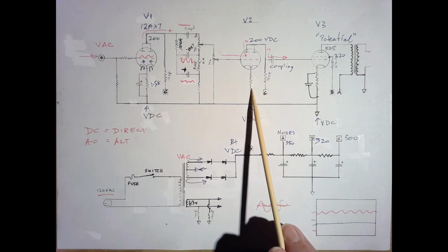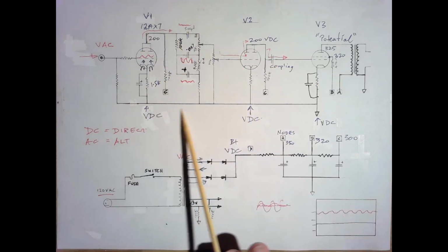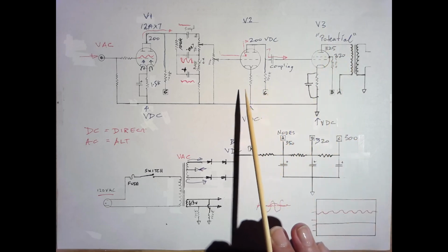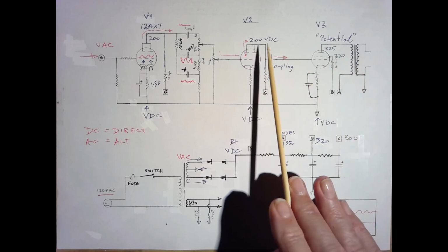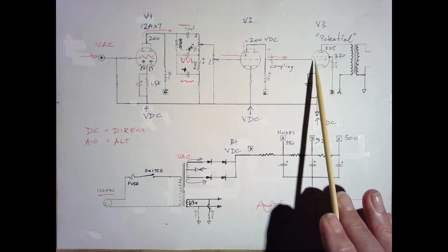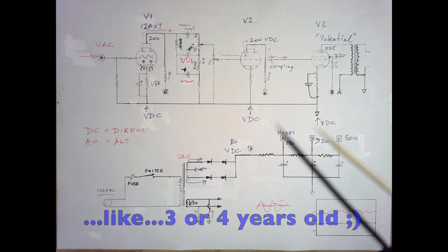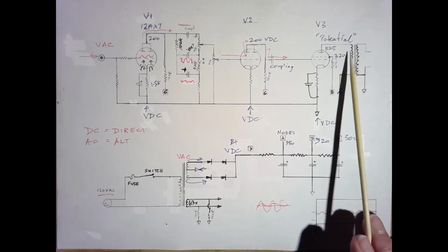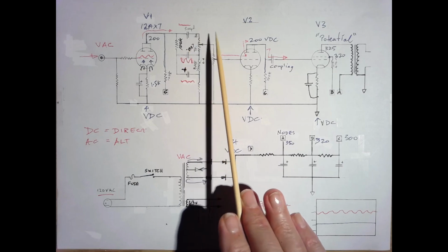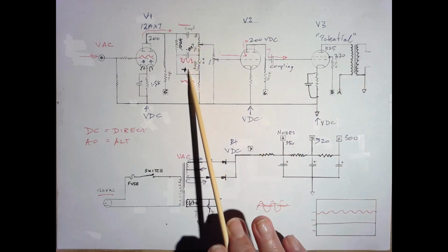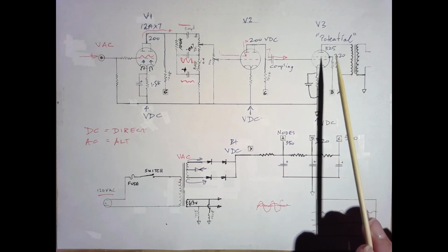You don't usually see a bypass capacitor on our driver because we're really intent on just driving the signal that we've created here straight into our tube. Otherwise you'll get a lot of overdrive. You might get too much gain here, and then you're going to be sending basically a high gain signal always in here, and all you might get is distortion, or you might get too much breakup at a very early stage. So here we see again, I'm going to remind you, there's this DC voltage potential all the way through the amp, our AC is riding over top of it all the way through, passing through all the capacitors and all the coupling caps, and it comes into our output tube.